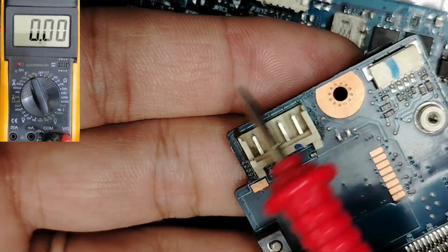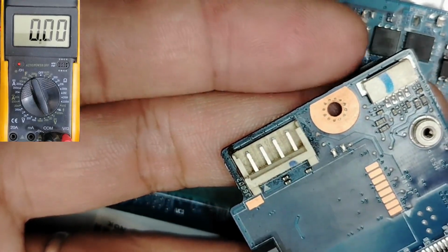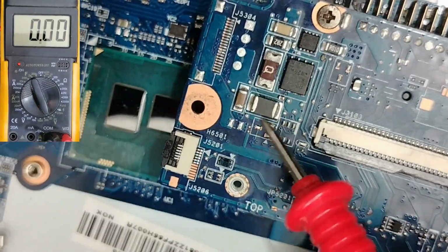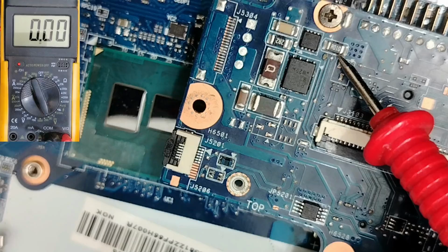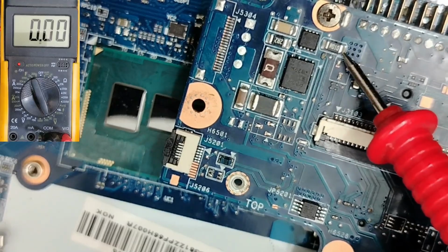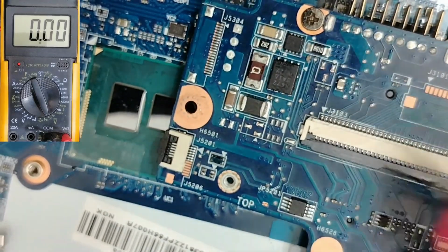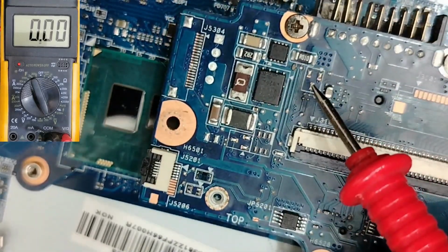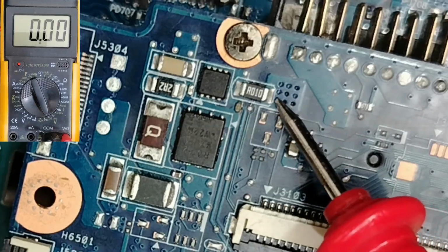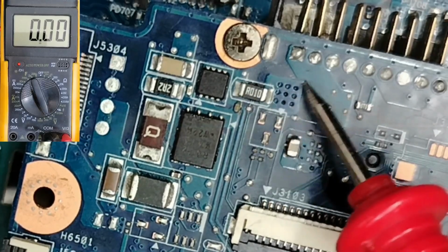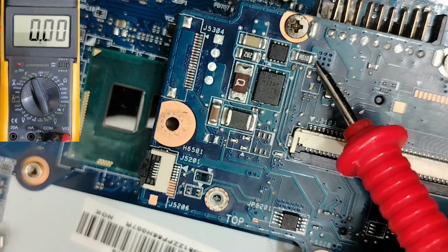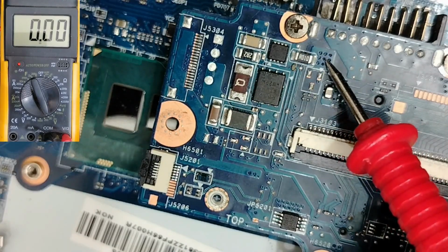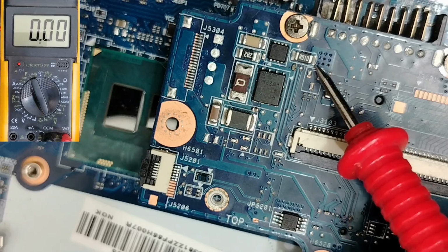For this board, for example, guys, that contains just this kind of integrated jack, if we go to the back, as you can see, we have the big inductor here, and we have the current sense resistor, R010. This is the current sense resistor. So here you have to find 19 volt. From this point, 19 volt will be distributed to all circuits in the motherboard. And the proof, guys, do you see here? We have these dots, which means 19 volt is distributed to the 3.3 volt circuit, RAM circuit, CPU circuit, chipset circuits, 1.8 volt circuit, BIOS circuit, the SIO, the peripherals, etc.